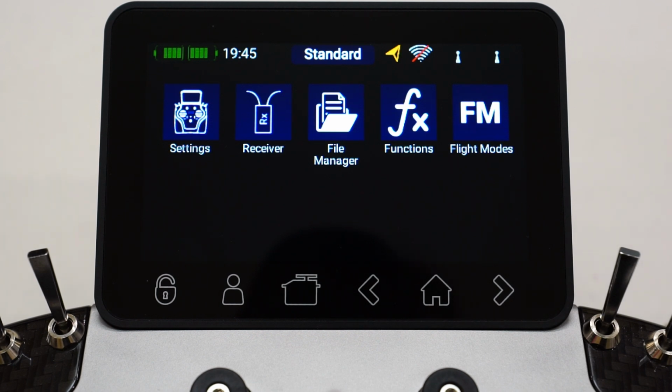So it's not just rates, but things like expo. In the Core, for instance, I'll show you when we have a look at the function menu. You can see we can adjust the curve. So in other words, the response of the flight surface, you can change that. We can also change the runtime of the servos. So if the servo's delayed, you might have a unique function that you need to delay the runtime speed of the servo. You can change those runtime speeds. So there's a whole lot of configuration options.